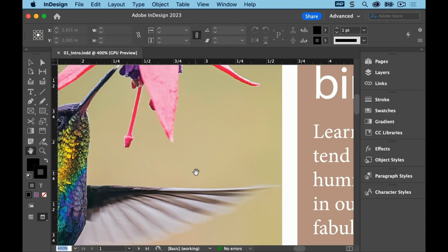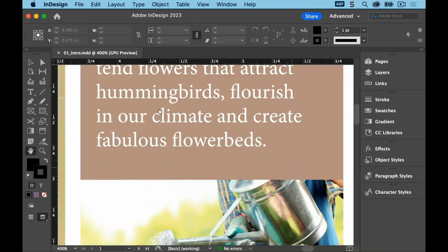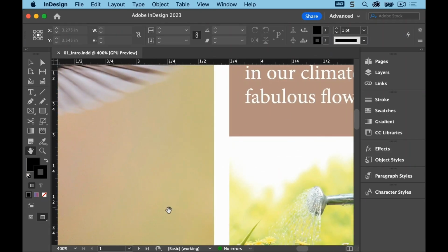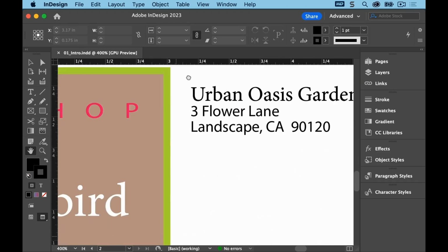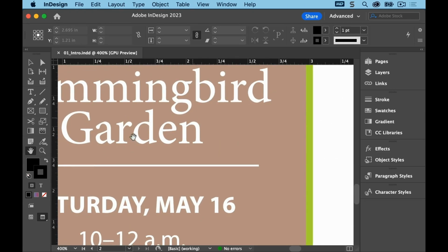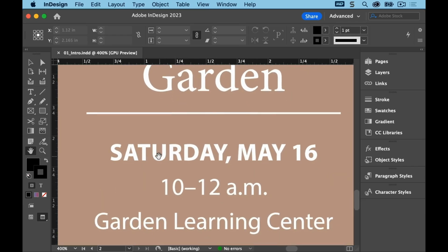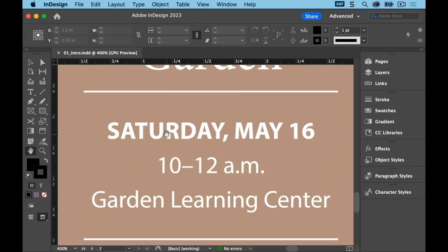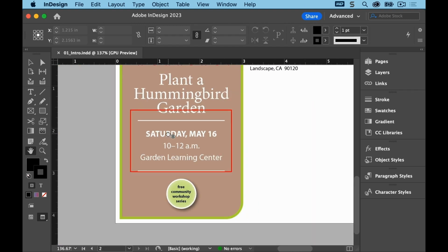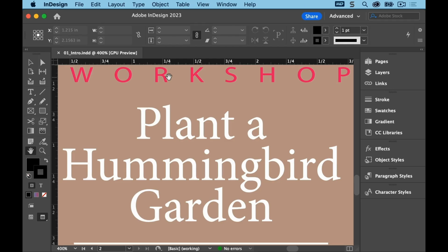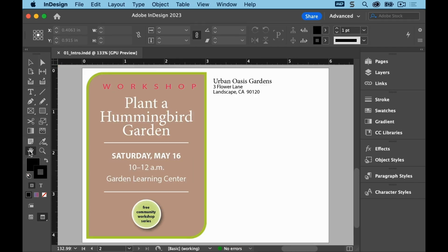Drag in any direction to move the page around, and then drag upward in the document window to display page 2. With the Hand tool still selected, click the page and hold the mouse button down to power zoom. With the mouse button still held down, drag to zoom into the area of the page you want to view. Double-click the Hand tool in the Tools panel to fit the page in the document window.